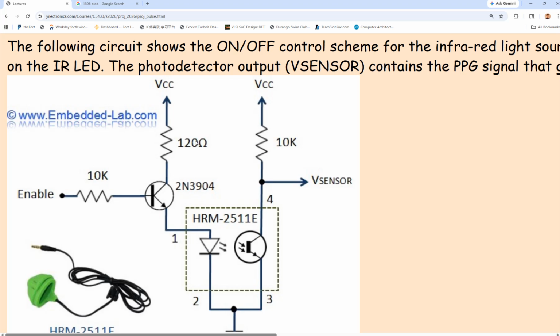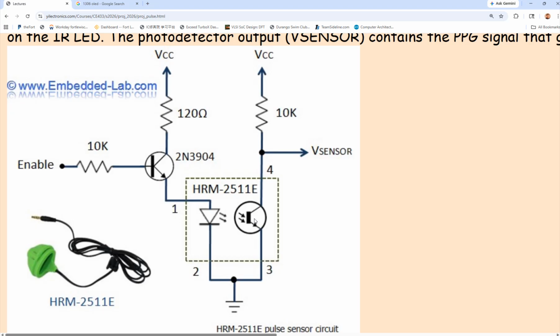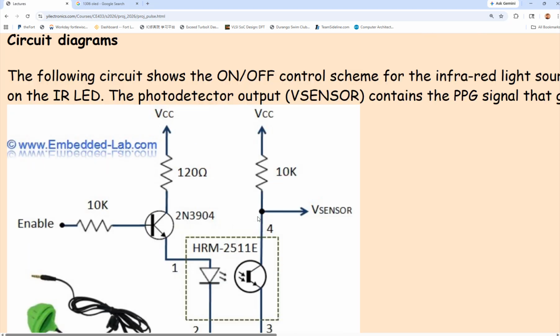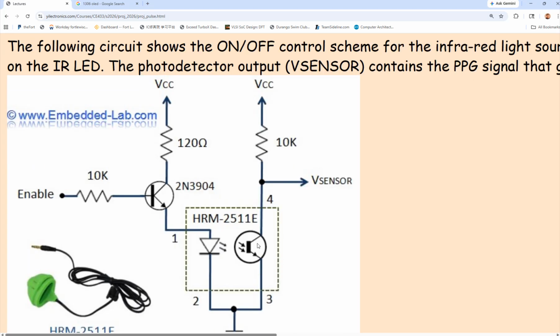It's not a pull up, so it's just like 120, 200, 300 probably are also fine, but this shouldn't be a pull up. This is a current limiting resistor. The current limiting resistor being connected into the circuit, current flows from top to bottom, and the emitter will emit our light, and it's going to be received by the receiver, and so this point will be shorted to ground and shows a low voltage, right? Depending on the amount of photons being received by the receiver, this voltage varies. Okay, so we're seeing the waves.